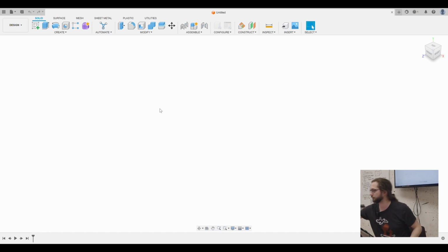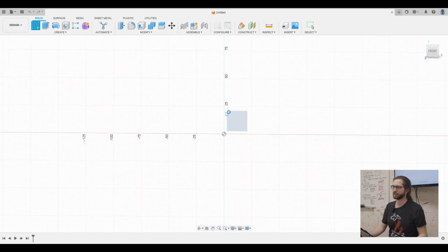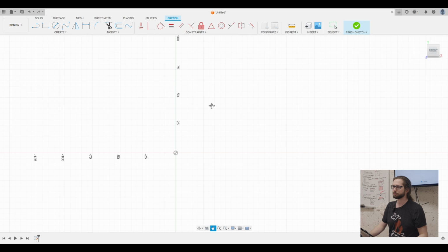So this is very good for round things. Almost all of this stuff started with a revolve command. And it lets you create some pretty interesting shapes because it doesn't just have to be a cylinder, right? Exactly. Some shapes you might want to start in the YX plane instead of the ZX plane, because most of the time you're envisioning these kinds of shapes from the side, right? So I'm going to start a sketch in the YX plane. So now I'm looking at it from the front.